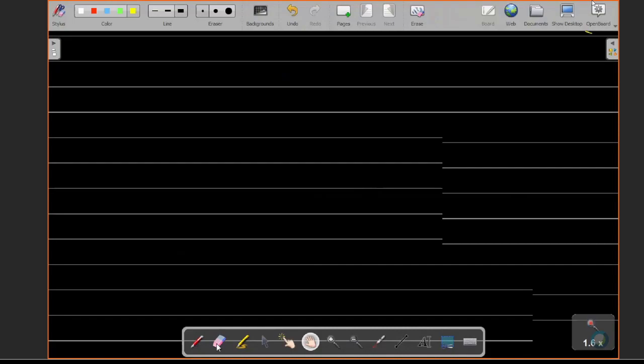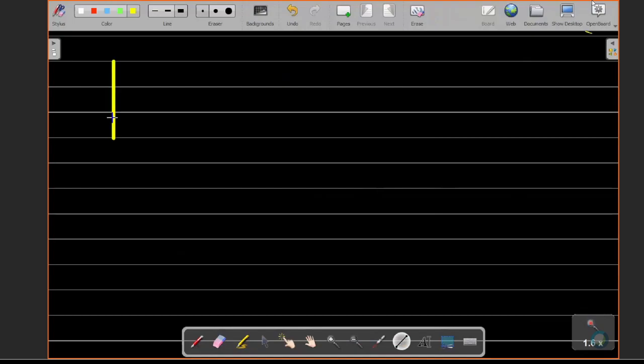So we are talking about a domain, and we will convert this domain into a number of nodes, number of cells or elements. You can call cells also elements. Say I'm converting this, and assume that they are uniform grids. So 3 by 3, I'm converting a complete domain into cells.